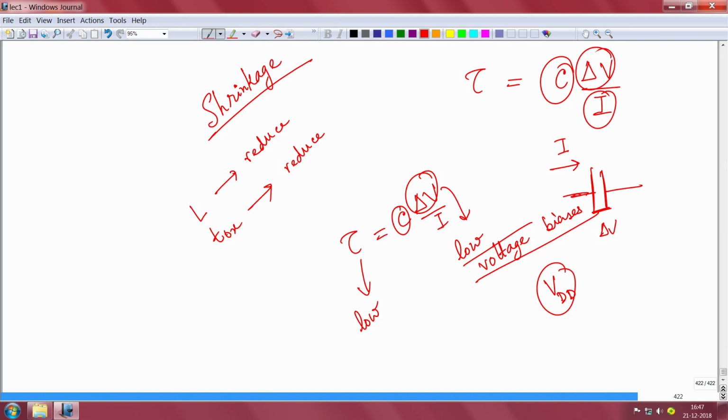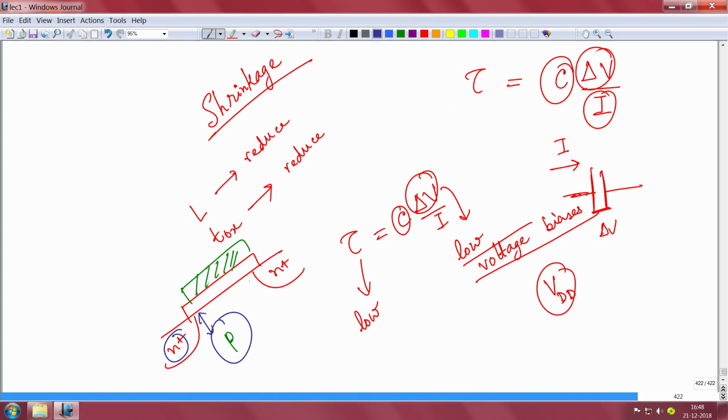They need not all be done to maintain the constant field or constant voltage, but for all the different dimensions of a MOSFET, you know, this is N plus, and then you have an oxide here, and then you have a metal here, sort of thing, right. Then this is the doping. So, this doping level, this depth of this junction, this doping of this junction, the junction depth, this length, the transistor length, this thickness, the gate oxide thickness, all these are reduced appropriately so as to ensure the device works as desirably as we want. Okay. So, this shrinking has been going on.